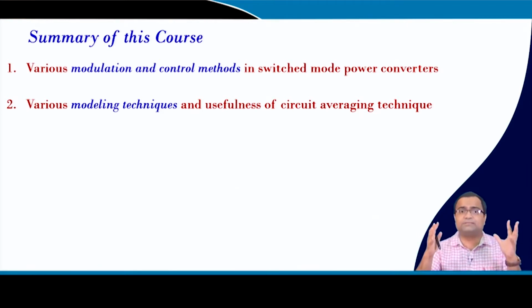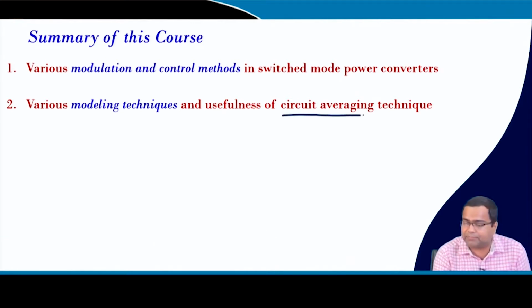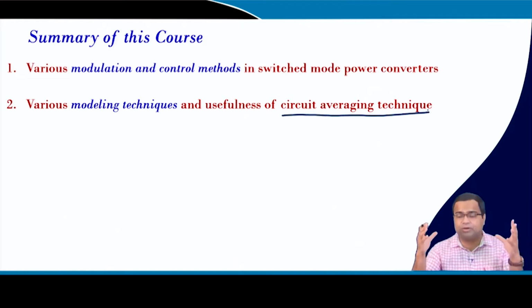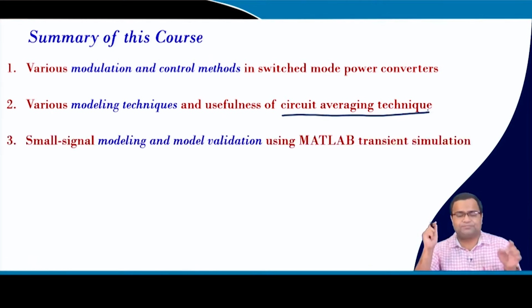We emphasized that for most of the small signal models using the circuit averaging technique, one important point I want to highlight is that this technique gives us physical insight, because we have often talked about input impedance, output impedance, audio susceptibility, and the control to output transfer function. So, if you want to understand from the circuit point of view how to shape the response, the circuit averaging technique as well as the equivalent circuit concept was very important.